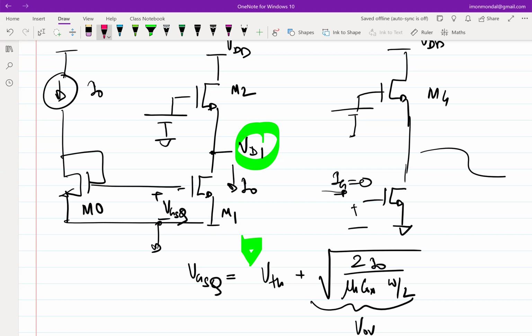Yeah, so VGS is changing, right? VGS is adjusting itself, right? So increasing the W by L, changing the size of M2, is not affecting the current. Hence, M2 is not setting the current in the stack. Okay, so the current is getting set by M1 and M2 is playing along. M2 is auto-adjusting its VGS, right?